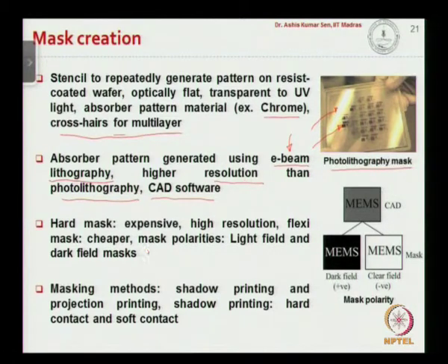Masks can be categorized as hard mask, okay, or soft mask. Hard masks are expensive, okay, because we use a material like quartz or glass to create these hard masks, and the resolution of the hard mask is typically much better as compared to the flexi mask.